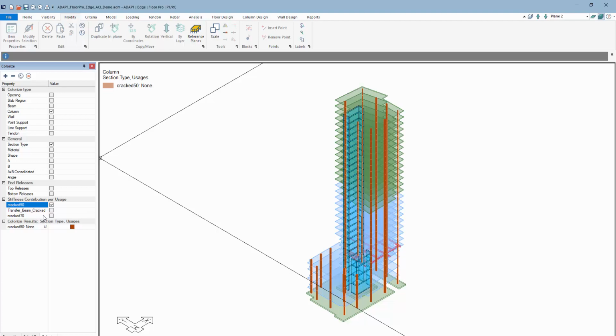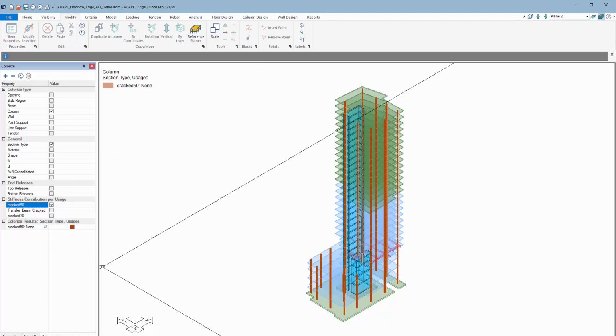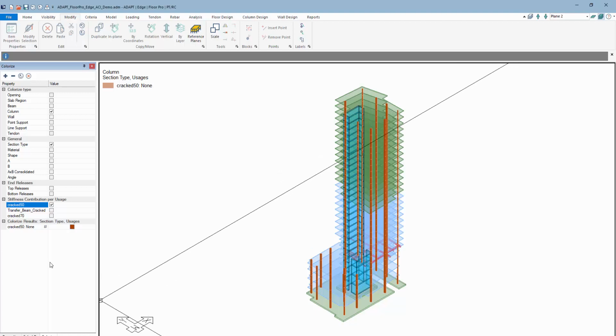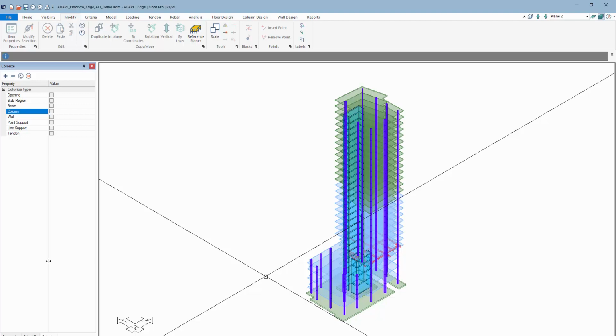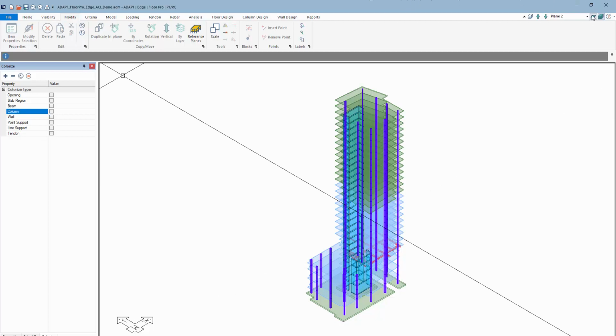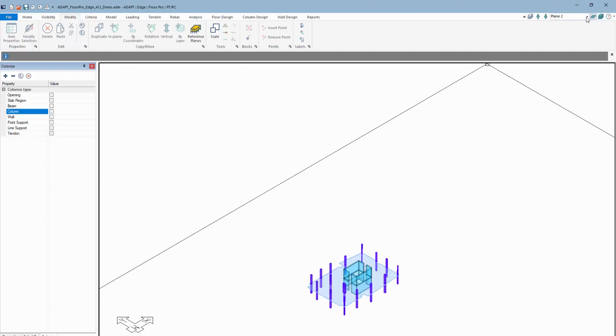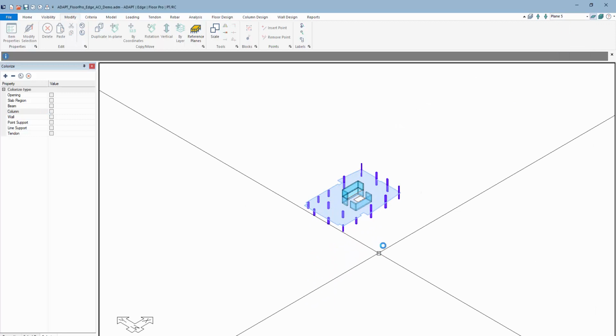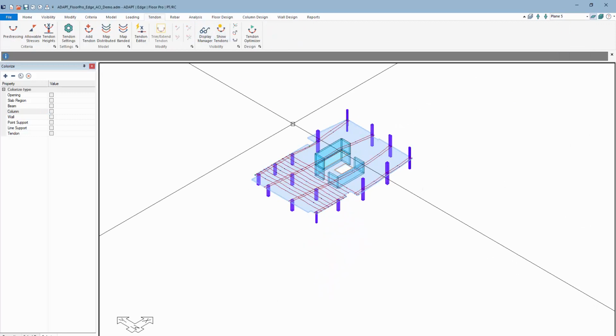So there are some really powerful visualization tools built into this property grid for the user to quickly sort and then select based on the sort using the colorization. One such application for this might be tendons, where we have tendons based on strand. You might have a variance in the number of strands, the total force, etc. So if I just go to a single level, this works in global or single level setting, and I'll just go here to floor number 5. I have some tendons there.